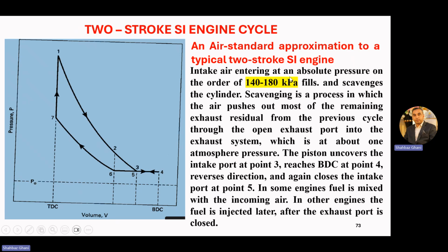Intake air enters at an absolute pressure on the order of 140 to 180 kilopascals. If you see this, this is P naught, the atmospheric pressure, but here the pressure is more. So air entering the cylinder is above atmospheric pressure. Remember this thing in the two-stroke cycle.